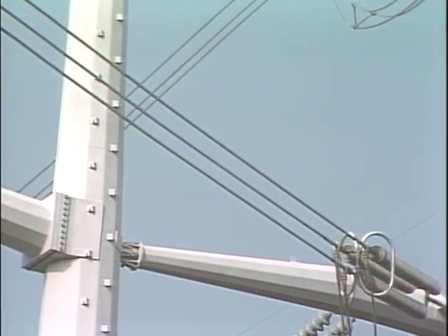Skin effect can be reduced to decrease the overall resistance and increase the AC current capacity of conductors by grouping conductors in bundles. Conductor bundles usually consist of 2 to 4 small conductors that make up one phase and are tied together electrically, but separated from each other physically.